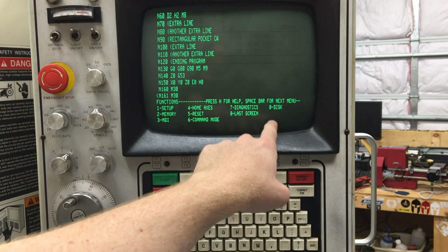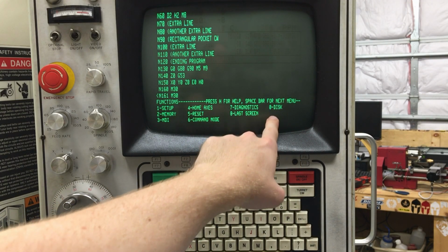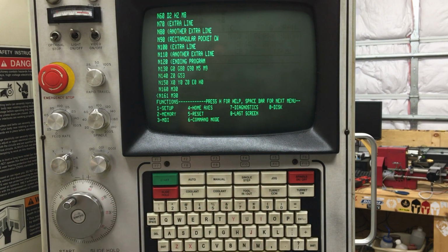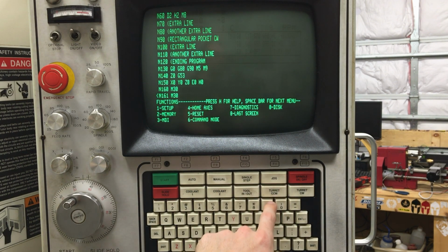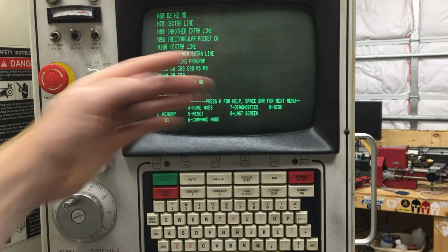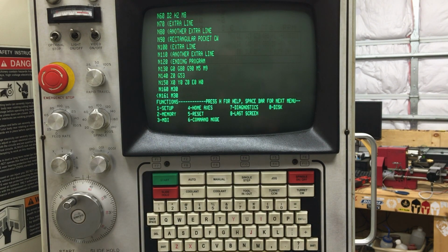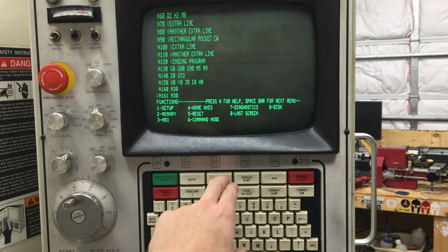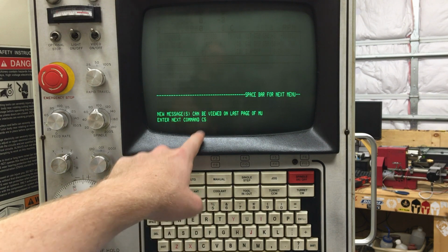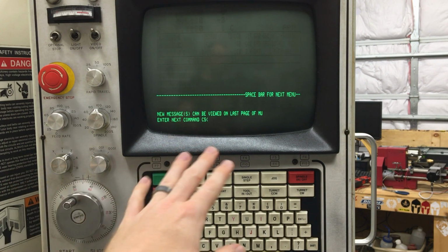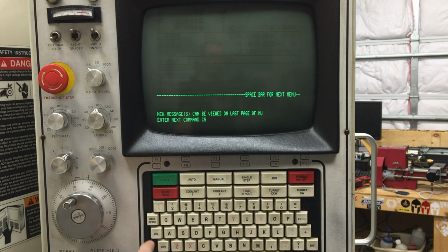But if you haven't, and you need to use it to set up your machine, first you go over to your machine, you align your cold start marks, X, Y, and Z, and you come over here and you push 9, and then you just go and run it. That's basically the same thing as if you were to go to the manual screen and type in CS when you're at the cold start position. I'm not there right now, so I'm not going to do it.